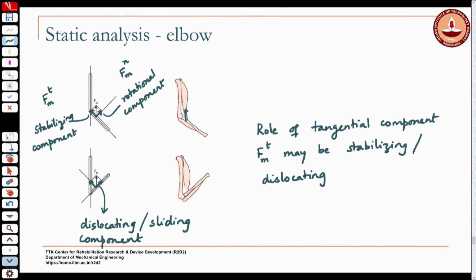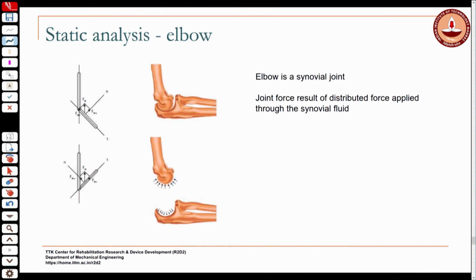So, if you look at the actual joint, you compute it as a pin joint, you compute it as a net force, we computed Fy as acting downwards, compressing the joint.